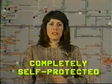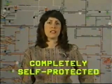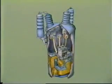By contrast, there are a variety of transformer designs that do include some or all of the necessary protective equipment. For example, in the completely self-protected design, as its name suggests, all protective devices are already mounted on the transformer. In this particular example, we can see the surge arrester, which is connected between the high voltage winding and ground.